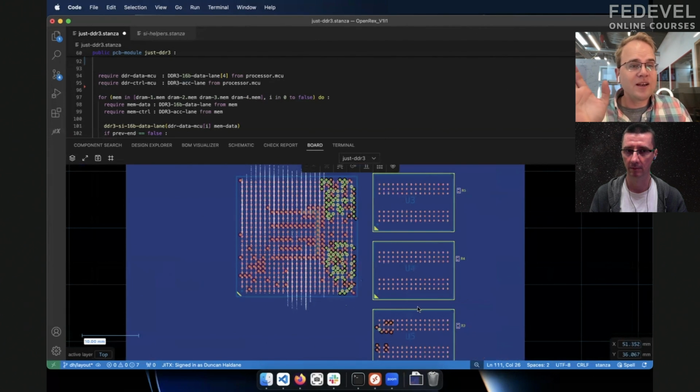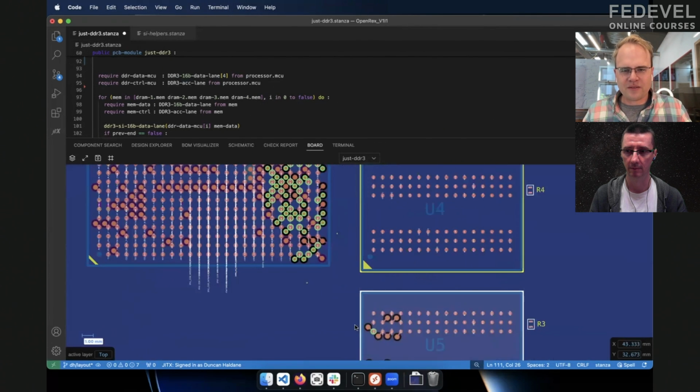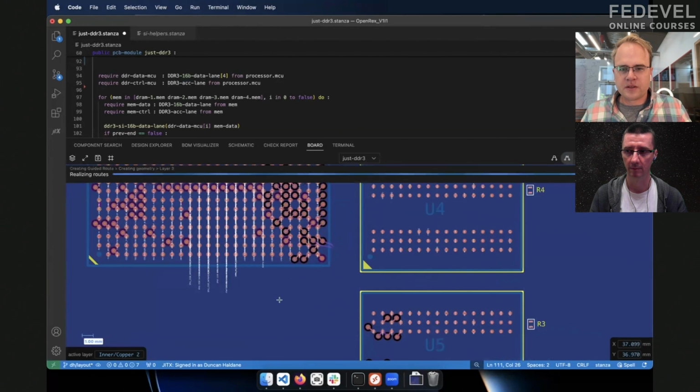So I haven't routed anything, because I'm going to build my schematic with the router. The usual flow is that I draw traces in from both sides, read the datasheet, edit my schematic, and then connect them, right? Instead of that, you can just pick a pin here, and maybe I'll pick one explicitly. All right, now I've made a trace.